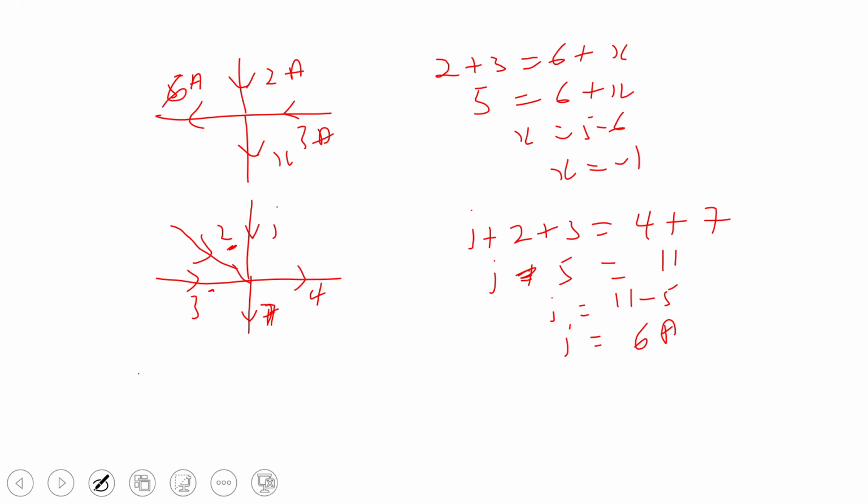So basically, this is how we use the Kirchhoff current law. And in most situations in circuit analysis, you will have maybe a node looking like this, where you have here say I1 and here say I2, and you would want to know maybe the current that is here, right? And sometimes you don't want to put maybe I3. I will explain more on why you don't want to do that. But maybe if I want to know the one that is here, I can see that I1 is entering the node and I2 is leaving, and the one I want to find, let me call it X, is also leaving.